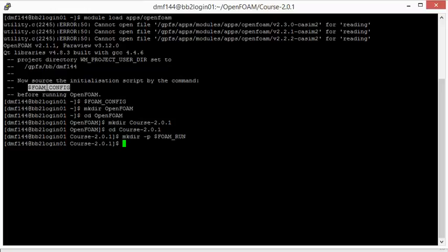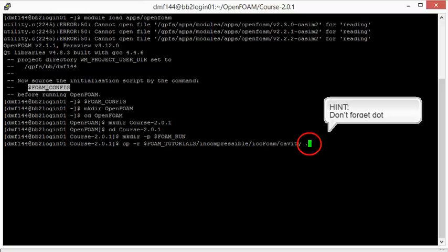Cases are set up in OpenFOAM by editing case files. A case being simulated involves data from mesh, field properties, control parameters, amongst other files required to run a simulation. Before I go any further, the case files associated with lid-driven cavity flow can be found in the OpenFOAM tutorials directory. Here, I will copy the cavity case to our home directory, modify the case, and run the simulation. To obtain the files, the following commands are used. Please note the dot at the end of the command line, meaning that the file will be copied in the current directory.